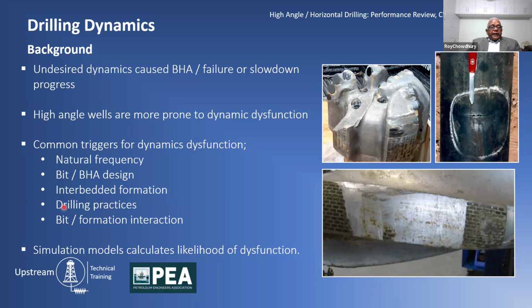Not to mention drilling practices: if the driller is not careful and not following good drilling practices, he could easily trigger some drilling dysfunction due to not following the proper process. And we'll talk about that in a bit. Bit and formation interaction is also very important. Some formations, harder formations specifically, are very prone to drilling dynamics issues.